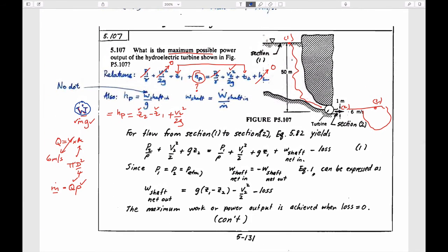Okay? So just like Bernoulli, you have to make sure you only have one unknown in your equation. And if you have two unknowns, you possibly have to use continuity. Mass flow rate upstream, mass flow rate downstream have to be equivalent, so it allows you to constrain, get one of the terms out if you have two values of velocities. All right?